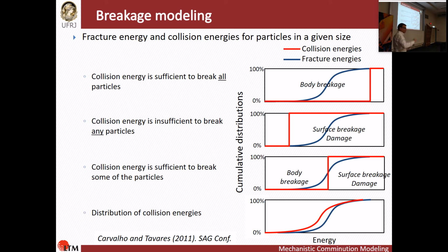It's just a simple equation you calculate. Well, what happens in practice starts to approach this, which is like a hammer mill or VSI. You're right in the middle here, but really, in practice in mills and crushers, it's not even that. It's actually two distributions that overlap, because the strength distribution is wide and the stressing energy distribution is wide. This is a typical problem that requires a convolution or a deconvolution to be able to take care of this.